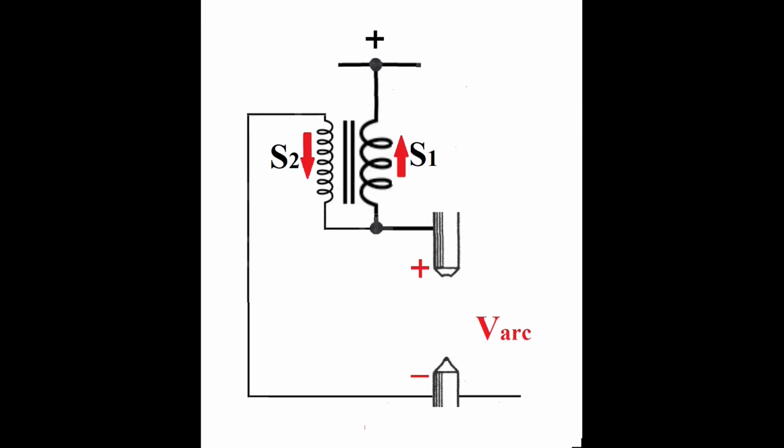As a result, more magnetizing current flows in S2. The magnetic field from S2 opposes that of S1, and the overall field is weakened, allowing gravity to begin to move the upper electrode down, closing the arc gap and reducing the weakening effect of S2. The original balance between the two magnetic fields is re-established, and the gap is brought back to the proper length. This early example of electric feedback control used magnetic levitation to control the arc.